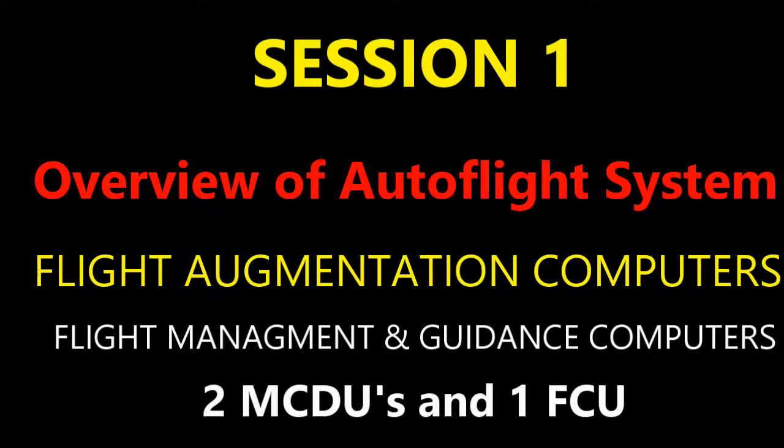Amber is typically your vertical flight management messages, and in white you'll have some flight instrument reconfiguration messages. They also can flash, so besides just staying put, you can also see flashing in white or in amber. And obviously if you have a master caution light that flashes, you're typically going to have that sound come on every so many seconds, and it'll continue until somebody does something to clear it.